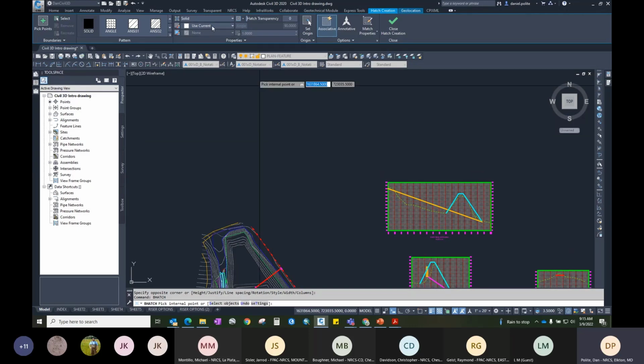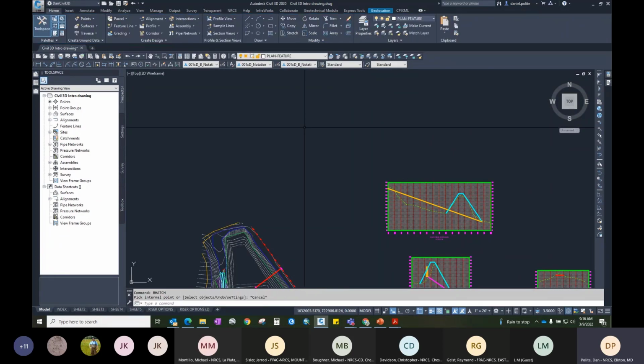Well, double check to make sure you're on the correct layer. That's really the main problem that I see, that, if you do an actual B hatch and you don't see it right away, you have a layer that's selected that's not on.